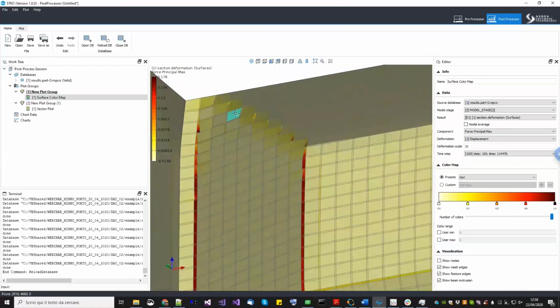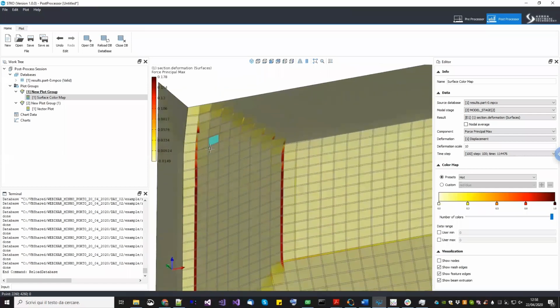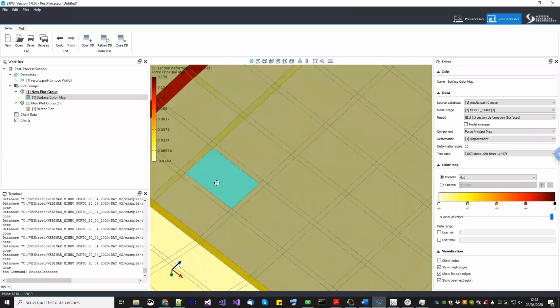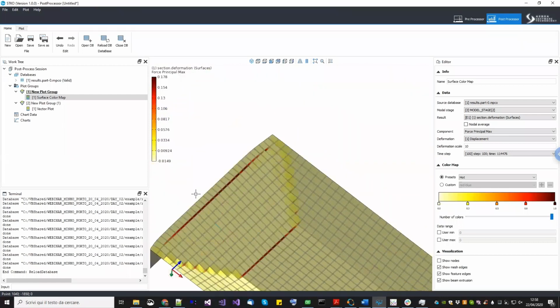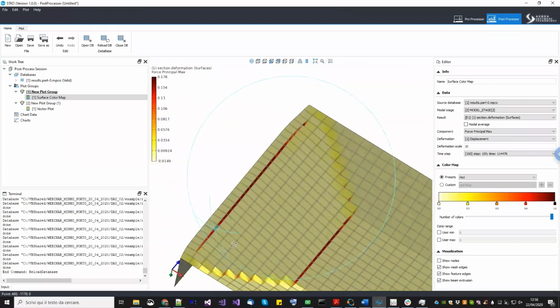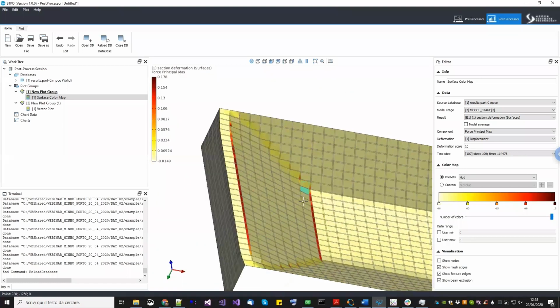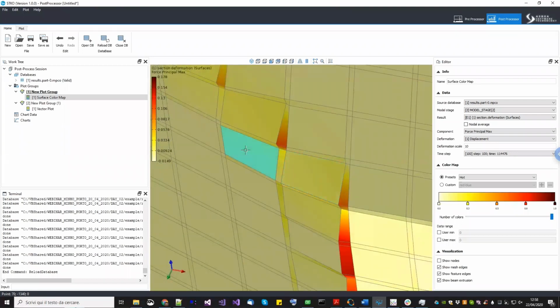So basically, in this example, you cannot see one brick that breaks over the other in the transverse direction. The only thing that you can see is a bending failure, like this one. For example, here you see a straight hinge failing in just pure bending, and the same here. You don't see the kind of failure that you have seen before. And in this case, the damage will be both in the mortar joint and in the bricks, as in this case. Let me show you.